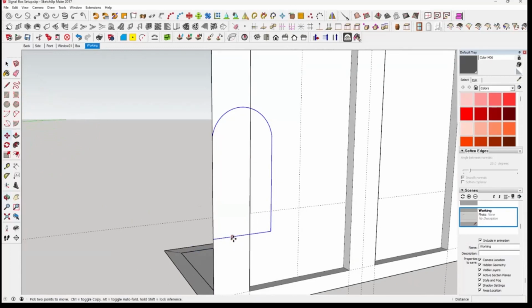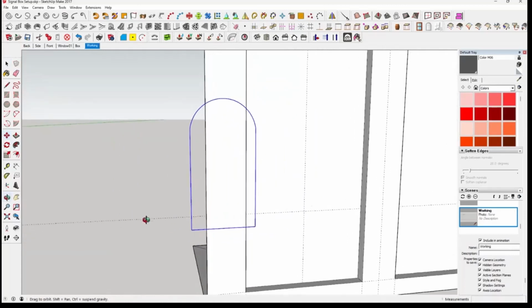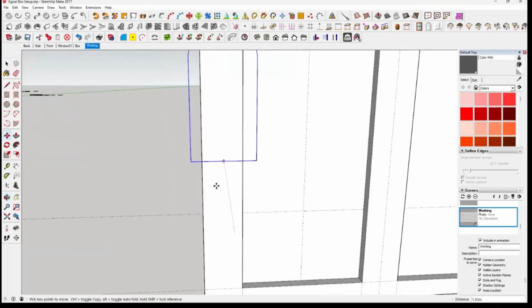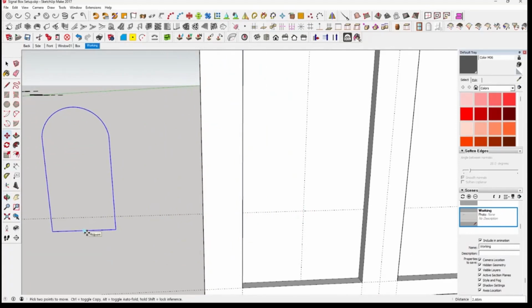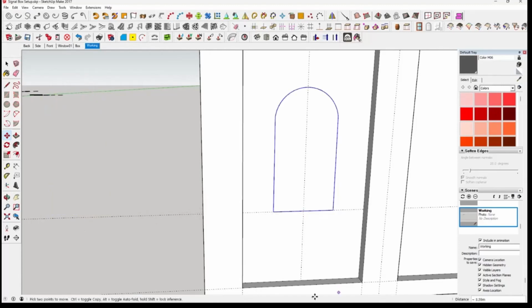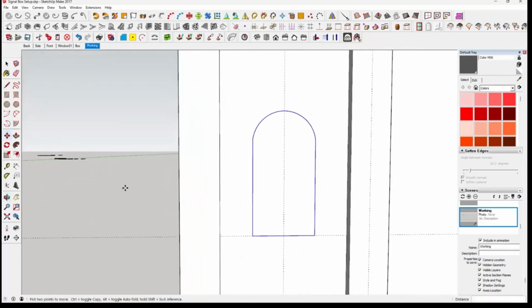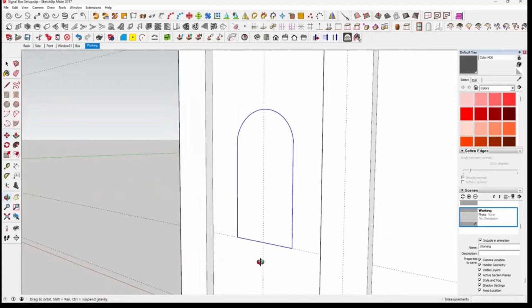So we have a move tool. We'll come in the center, find the center of the object here. A good shortcut is when you want to place something, you click on the middle, midpoint, press the up arrow, and then go across, find where you want to place it, press the up arrow, and then enter, and you're on there. And that works with all objects. So you could have an object in the distance, press the up arrow, find where you want to place it, press the up arrow again, press enter, jobs are good.